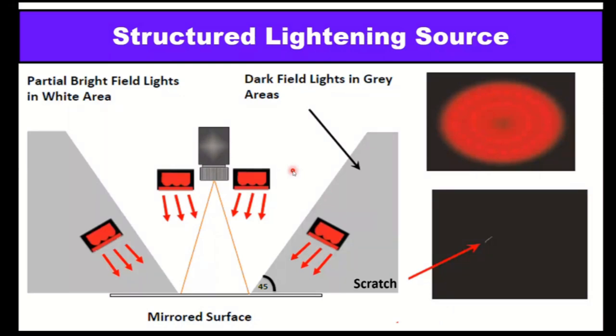In such cases, a special arrangement is done for the structured lighting source, wherein multiple sources can throw light, create dark and opaque zones, and the region of interest is carefully highlighted. Even colors are managed or color filters are applied, and only the required area will be shown.